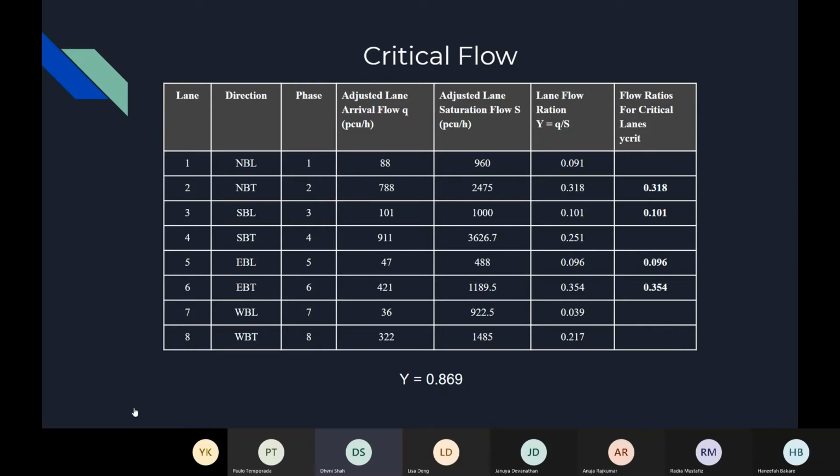Saturation flow was calculated by counting the number of vehicles that crossed the stop lines for each cycle in each direction of the intersection at 5-second increments. This was only calculated for protected left and through movements, and right turns were neglected.